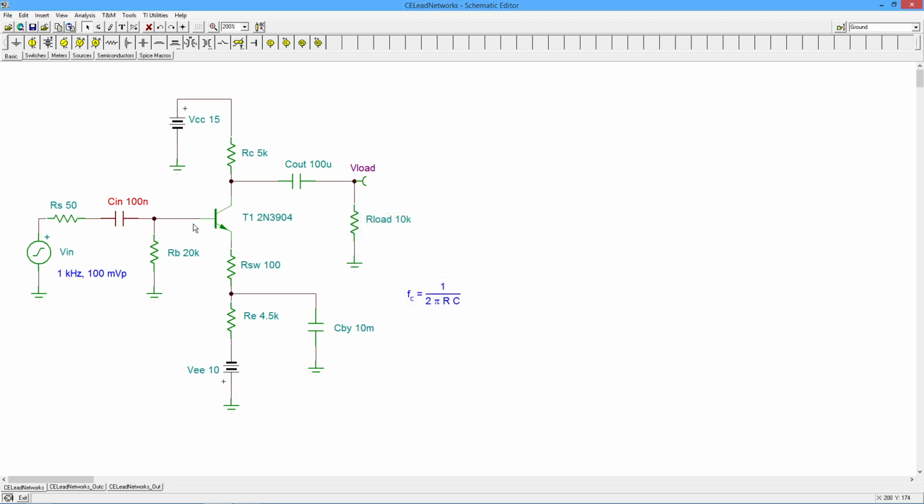Now we just have to figure out what this impedance is. Well, you're going to have RB in parallel with Z in base. What's Z in base? Well, Z in base is beta times (R prime E plus RE). Your RE is 100 ohms. Your R prime we already estimated to be about 13 ohms, right? So you've got 113 ohms times the beta.